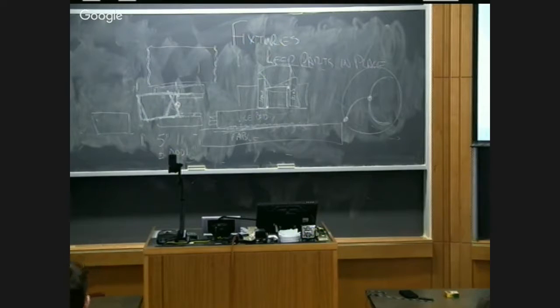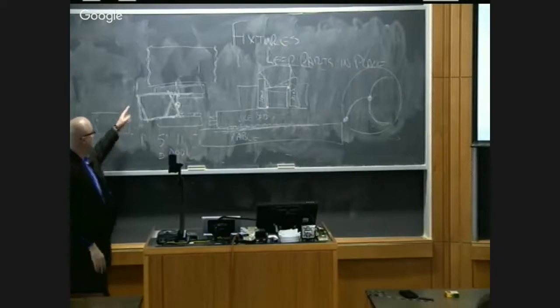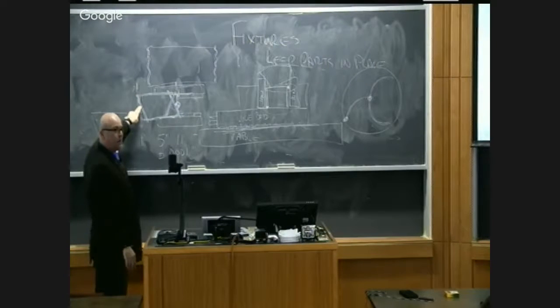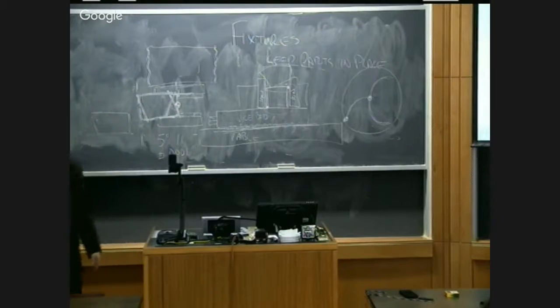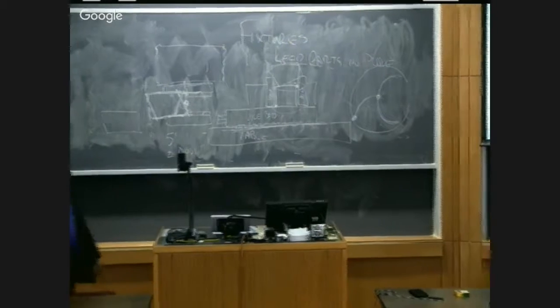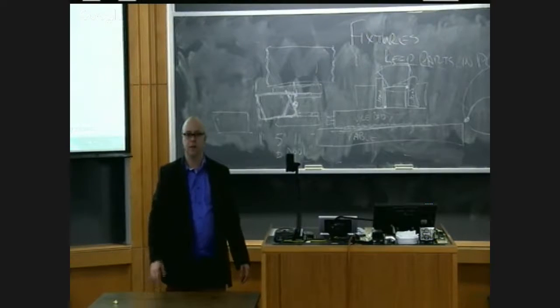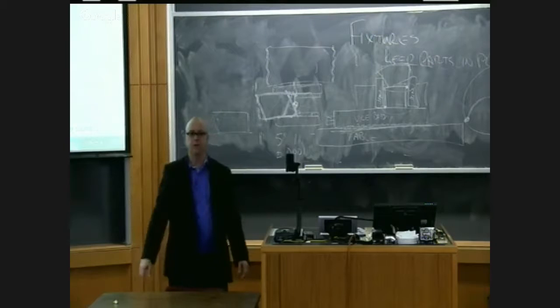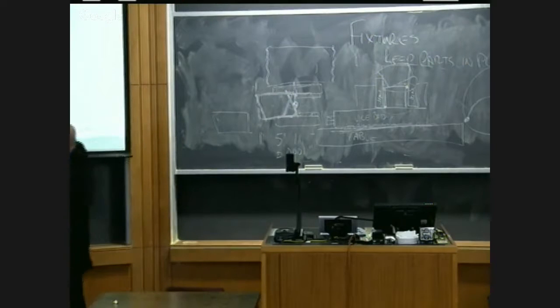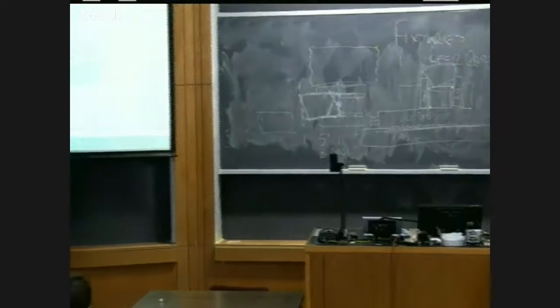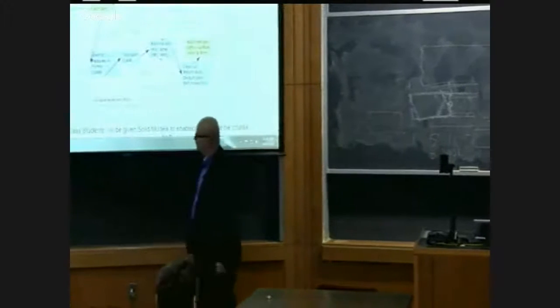The first exercise, when we're flipping the part over, it mattered where we put the origin, right? Because if we tried to make them 5 inches long, and we kept putting the origin out here on this side, how would we make it 5 inches long? You could do it, but how would you do it? Cut, check, cut, check, cut, check, right? So you'd have to iteratively approach it. Once we figure out our tool paths, we put everything in the machine tool, we can make our finished parts.